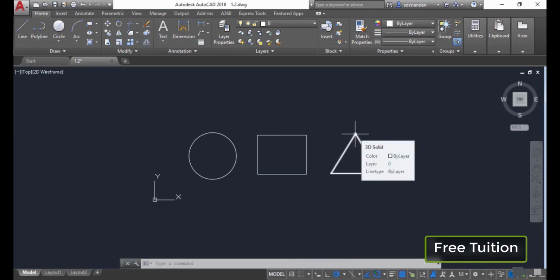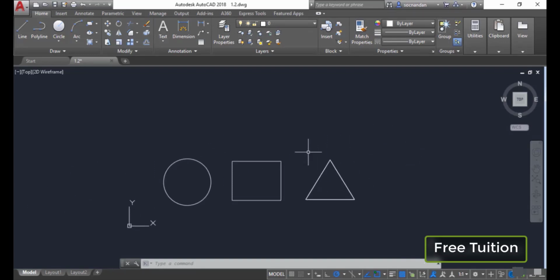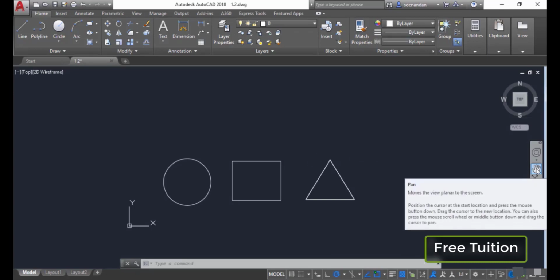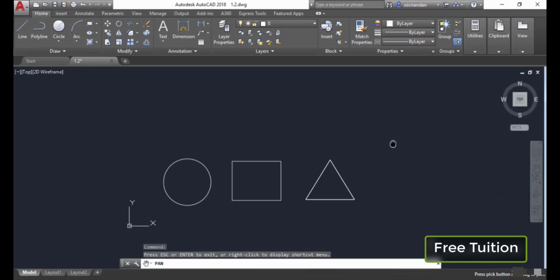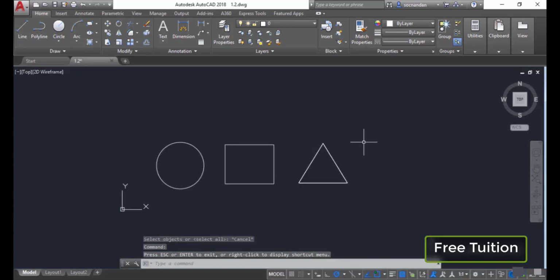In order to pan this drawing or move this drawing in the drawing area, simply press and hold the mouse wheel, and the cursor will change into this hand, and now you can move it in the drawing area like this. You can also access these navigation tools directly from the navigation bar. Here we have this pan tool. Simply select it, and now you'll be able to pan in the drawing.